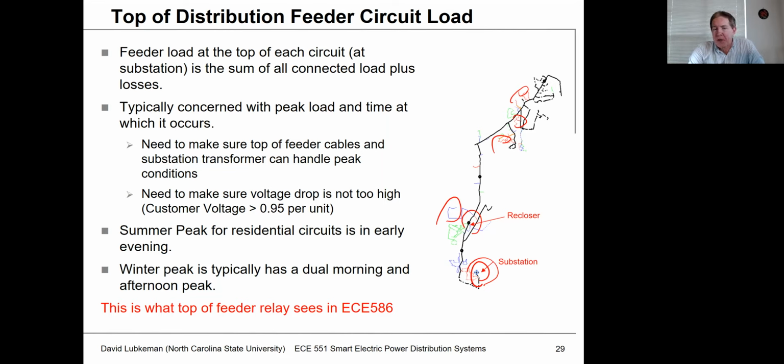And so if we looked at the total amount of load in the circuit, we'd be concerned about, well, do I have any overloads? Am I loading something up too much where it might burn up? Or do I have issues with low voltage, especially at the ends of the circuit? All right, so this is why we would do the analysis that we do, all based on having a model for the net load in the circuit.